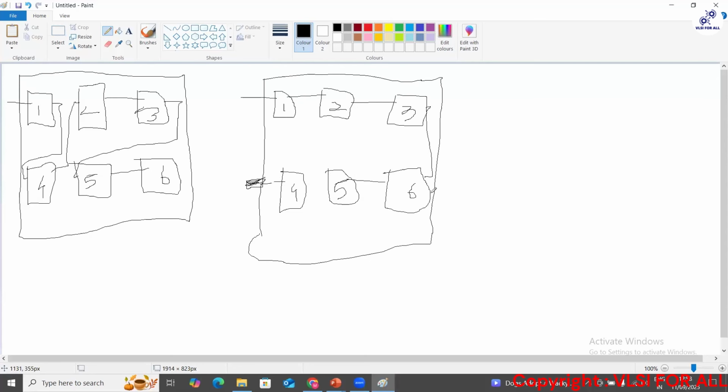Even it will help me to increase my area availability for placing the different kinds of other cells. Once I have done the scan chain reordering, I'll dump a DEF which is called a Scandef. This is not matching with the primary Scandef provided by the DFT team, because I have reordered my scan chain logic, and you have to inform the DFT team. So you will give this modified Scandef as an input to your DFT team.